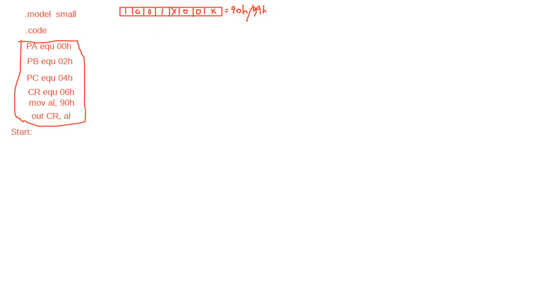Now first of all we have to read the ADC. The ADC is analog to digital data, and it is connected to port A. So we call the ADC, we call a subprogram. Call ADC. And then we will compare it. CMP, compare AL, because in the main flowchart you can see all the things. First of all we read the ADC, so call ADC, another subprogram.